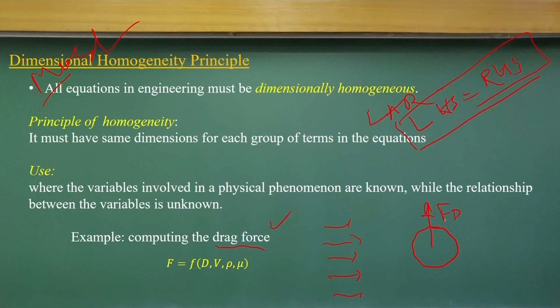If it is the velocity V, the diameter of the cylinder, and the drag force Fd that I am looking at, then two other properties also matter: rho and mu, the viscosity. It depends upon whether you have air or water, so the density varies and the viscosity varies.